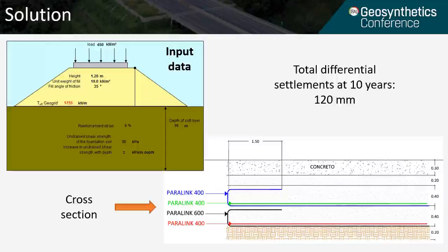The geogrid used in this project was a high-strength uniaxial geogrid characterized by a high-tenacity polyester core with a low linear density polyethylene coating. This coating is resistant to physical, chemical, and biological conditions found in reinforced soil structures. The reinforced granular mattress layout consisted of a 3.28 feet thick aggregate layer with two sets of transversally installed high-strength uniaxial geogrids.